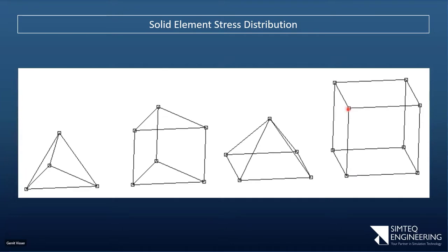Because to do that, for one of those triangular faces, let's say I'd have to split it along there or along there. The moment I look at the deformed shape, if these diagonal nodes lift up, I get some kind of a curved shape. If I look at triangular faces there, all of those triangular faces stay perfectly flat.